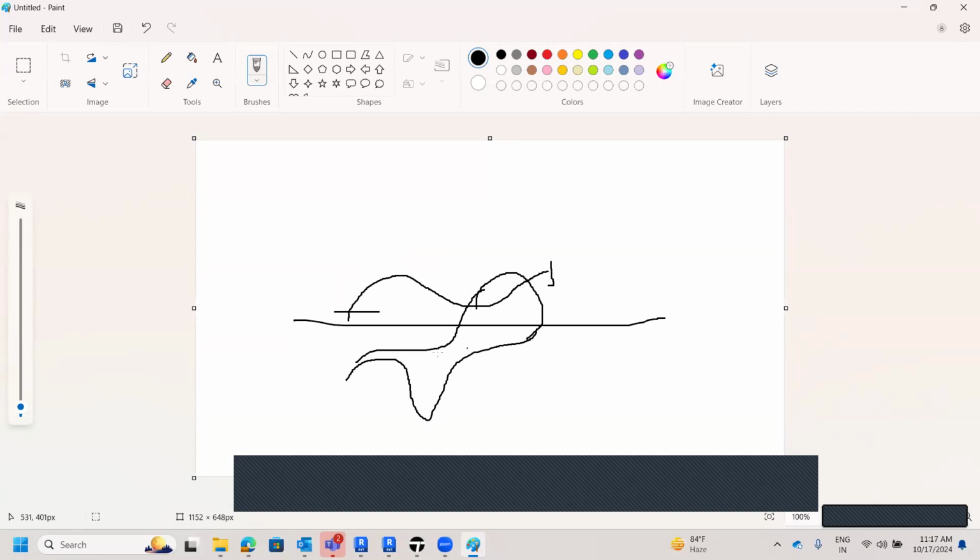So if I'm going to create something like this parametric sort of shell structure, then the adaptive families come into place, so that you can flexibly place them onto the entire surface which you are going to create. So the first step to work with this particular adaptive modeling part is to have a sketch or a surface.